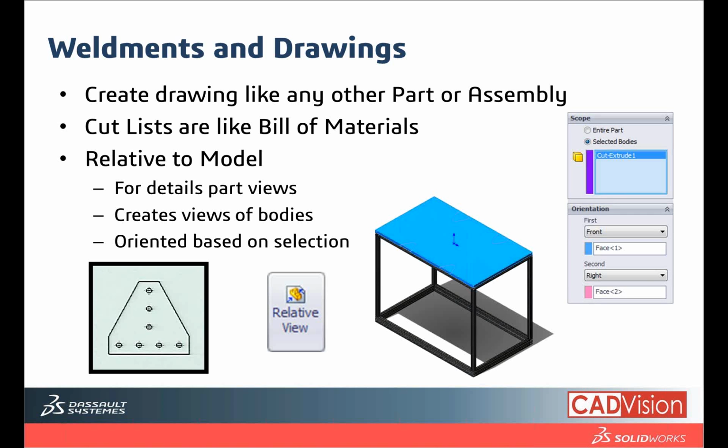The next thing will be to use the corner treatments, to make each edge have the correct outputs. And then if there are any structures intersecting with each other, use the manual trim to trim them together. You can select which body to discard or which body to keep. The next thing will be updating your cut list.